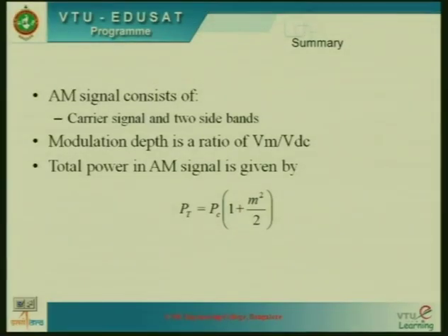And then we also identified that an AM signal consists of a carrier signal and two side bands. Okay. So, it is a very interesting logic there. Whenever you take a modulating data, that is your message, and multiply it with your carrier, you automatically generate an AM signal that consists of two side bands. To ensure that you also have the carrier along with it, you add the carrier to that signal, and the carrier along with these two side bands is transmitted from the base station.